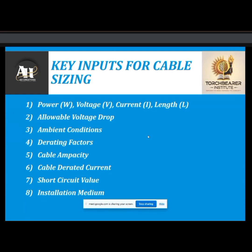For the MV AC cable we use the output current of the MV switchgear, and for the HV we use the current from the main substation transformer, like the 220 kV voltage level. They give us the current value. On that basis we will design our cable sizing.